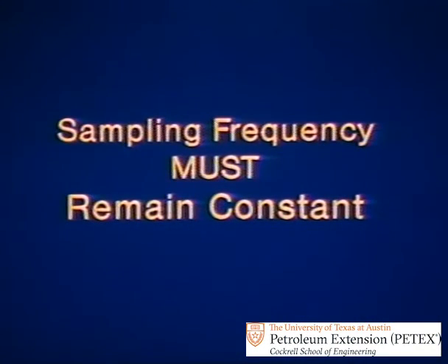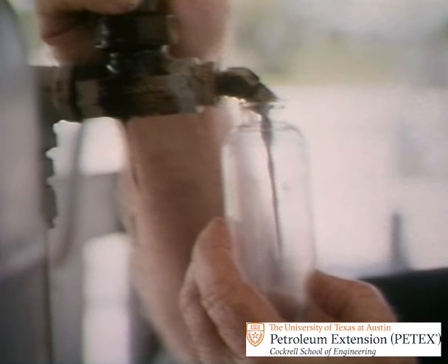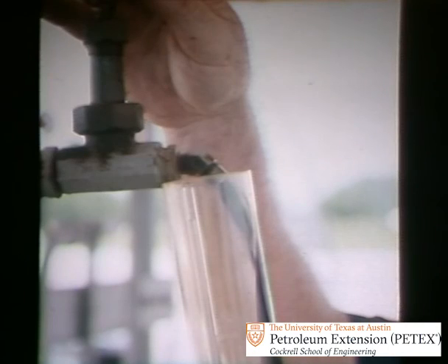The sampling frequency must remain constant during a sampling period. Changing the frequency affects the accuracy when sampling a variable stream. Samples must be withdrawn and tested before you remove any other liquid from the sample receiver, and take the test portion only after all of the sample is thoroughly mixed. Purge the draw valve and piping before you take a sample. Also, don't let any rain, dirt, or condensation into the sample receiver.